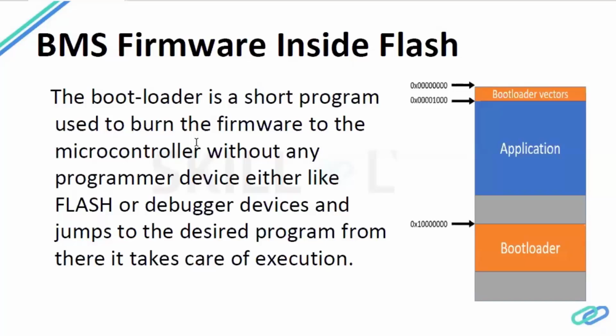Bootloader helps to write the firmware inside the flash memory, because if you have a washing machine, you can't have an OTA system enabled on the washing machine. If there is any error coming to your washing machine, someone will come and check the microcontroller by checking some hardware and putting in some debug software. So you have to use some hardware to update the firmware.